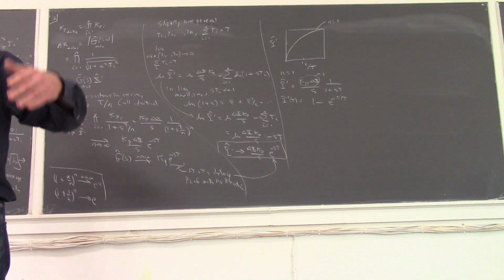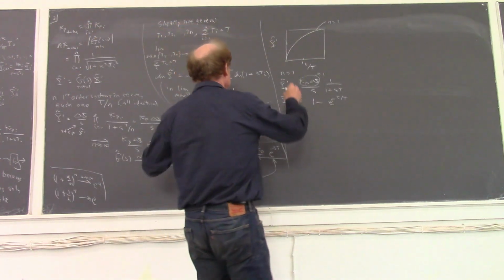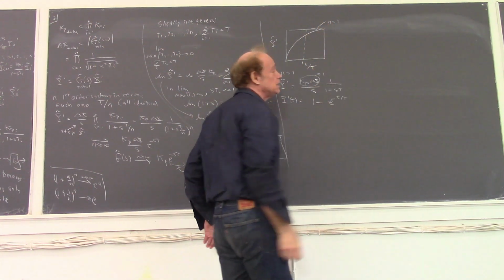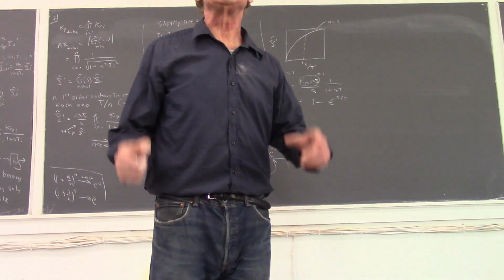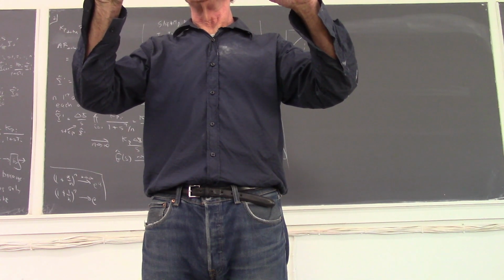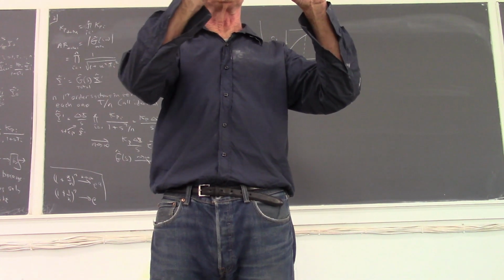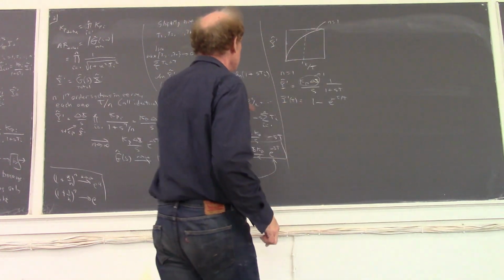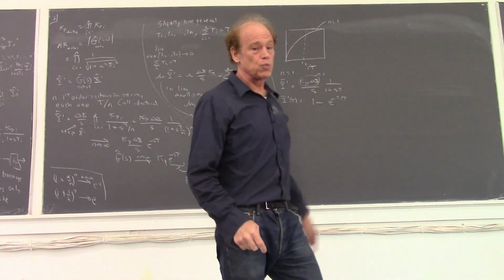We don't know anything about the change. But when t is greater than T, it's just 0 or 1. What does that mean? I have a plug flow reactor and I do a step change in the input. The output looks the same until tau seconds have passed by, and then the output also has the step. So it's 0 here, and then it's 1 there.